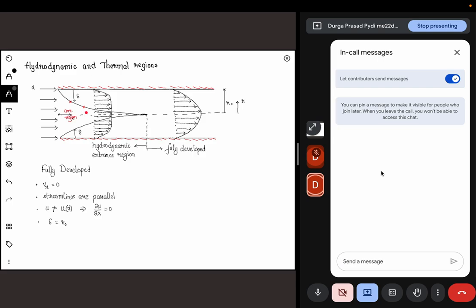where the fluid will accelerate, and then this boundary layer keeps growing, and eventually they will reach a point where both of these will match together, right? So here is the most important point that you need to be considering. Depending on what you are looking at, this can be an external or an internal flow. If you are restricting yourself to the region very close to this one, how do you know? It is when these two surfaces, the separation between the surfaces versus the length of the walls that you are considering, depending on that ratio, this can either be an external flow or an internal flow.